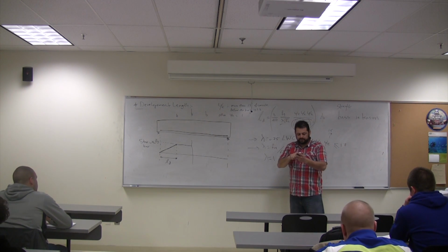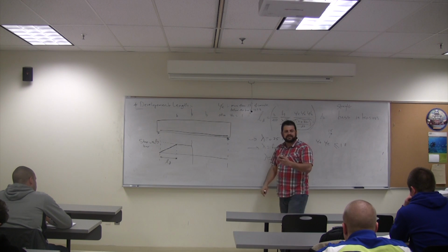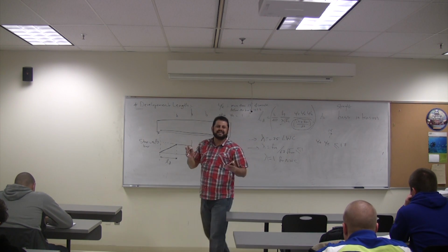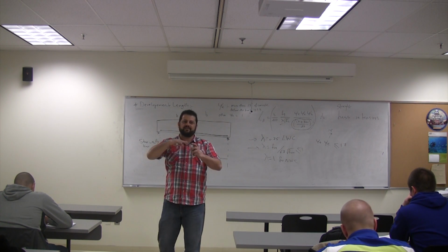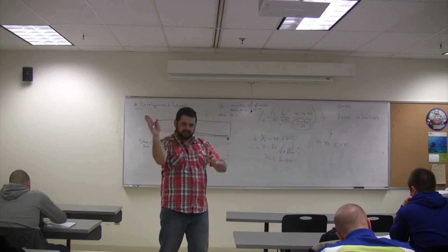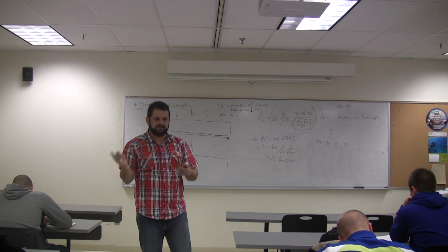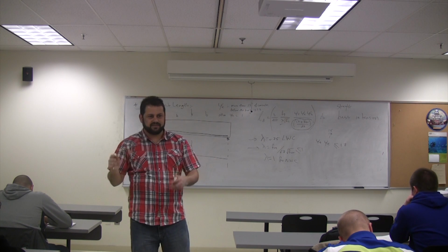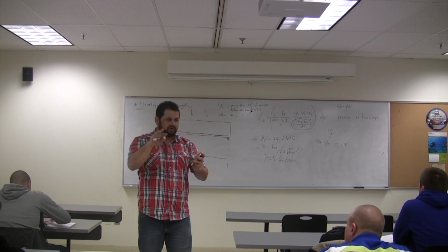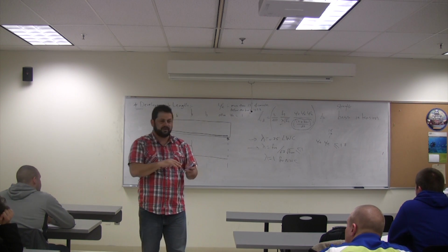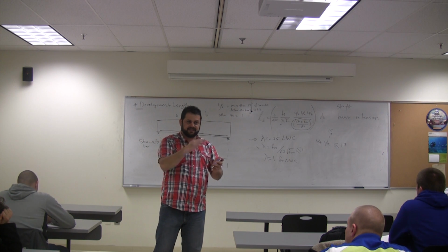Okay, I'm going to read for you. Transverse reinforcement index. It's an index that depends on whether you have transverse reinforcement within the development length or not. Usually you don't have this information. And it has an annoying formula, but there is a formula you can use to calculate it. And the chance of making a mistake in that formula is high.